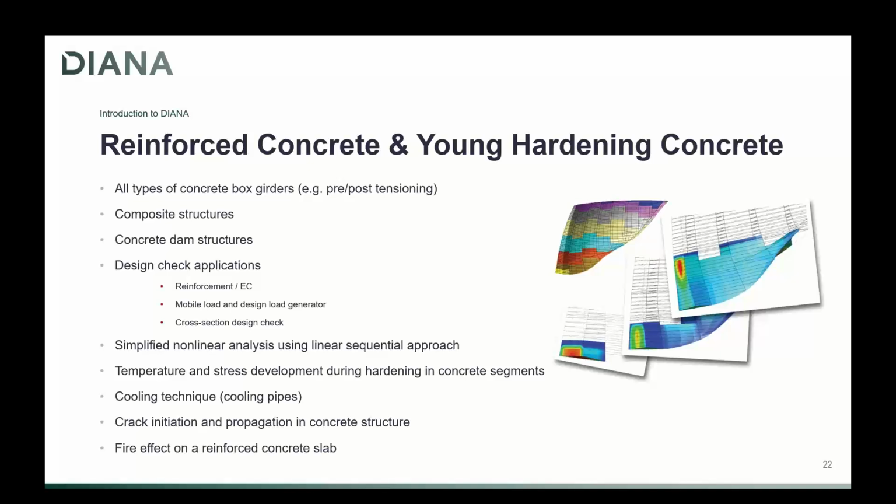Temperature and stress coupling let you analyze how the concrete goes through aging. This is also very important. Cooling pipes is also another powerful feature that we offer in both 2D and 3D in order to control the hydration process. Crack initiation and propagation in concrete, one of the powerful features in Diana, and also fire effect, how the fire could affect the durability of your structure. And I would say to get an answer to this question, Diana is the right tool.